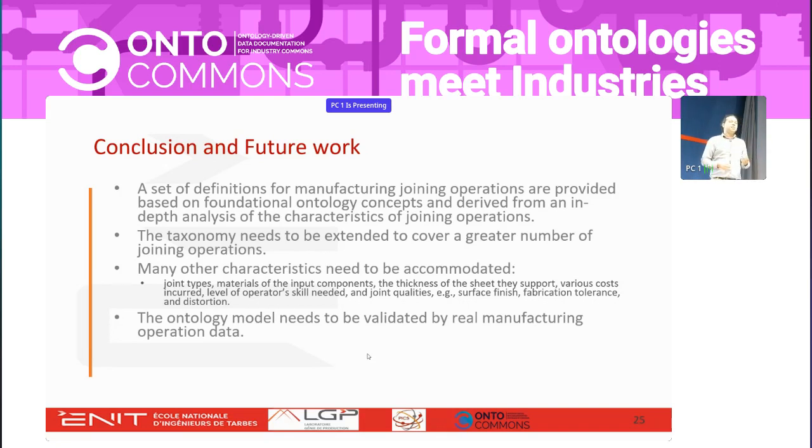So, for example, you have some consumable you need to use. In welding, you need to use some inert gas, say MIG, where an inert gas flows around the welding torch or is supplied from outside. It helps in protecting the weld from the outside environment, and this only happens during the melting and solidification. So the function of that particular resource, the inert gas or say slag or something like that, is of course realized by the process of melting and solidification. Of course, not exactly melting and solidification, it actually creates a protective layer.